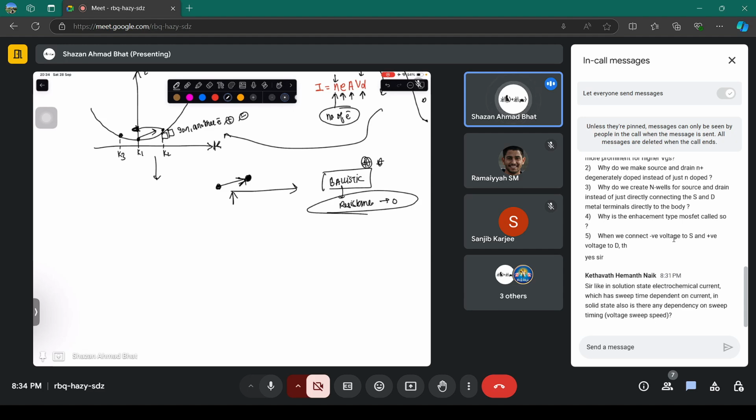But we are talking here about diffusive transistors. Diffusive means the motion of the electrons is like a diffusion, a random motion with random scattering events, which randomizes the momentum of the electron. This k is associated with the momentum of the electron. k is called the wave vector, but the momentum of the electron is h bar times k, quantum mechanical. You have studied it in initial lectures.